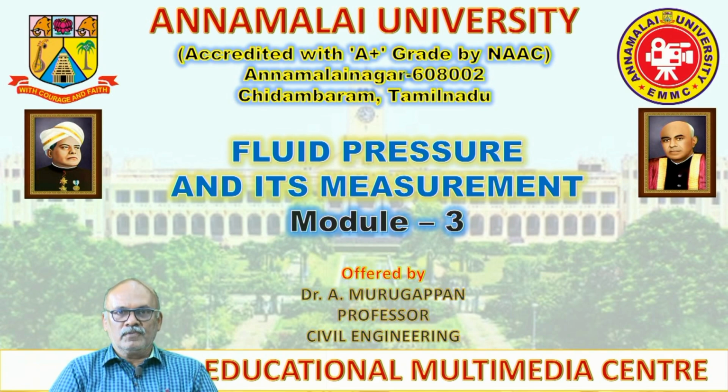That is, we can take absolute zero, that is complete vacuum, the point where the bare minimum pressure can exist, or atmospheric pressure as the datum. When we take atmospheric pressure as the datum, atmospheric pressure is treated as equal to 0 and we report the pressure as above atmospheric or below atmospheric. So above atmospheric it is positive, below atmospheric it is negative, that is gauge negative, and above atmospheric gauge positive.